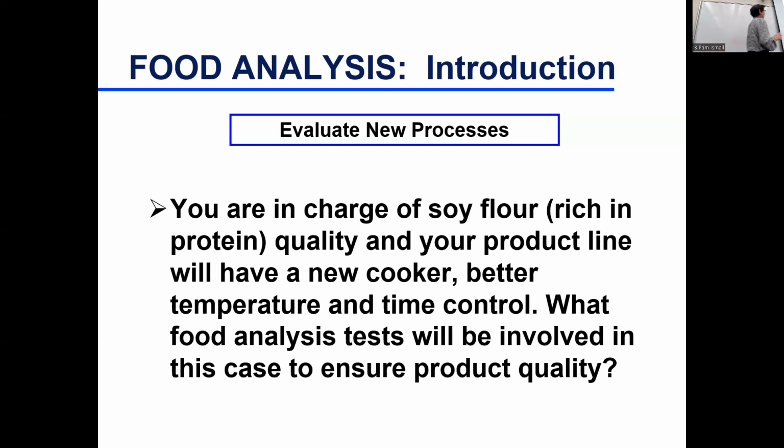So the main issue was the protein got overheated, it denatured, it polymerized, and it was hard to digest by the microbes. So they had to go back and look at the engineering aspect of things, look at the temperature and the time, and how they can control it, to bring back the parameters the way the previous soy flour was produced.